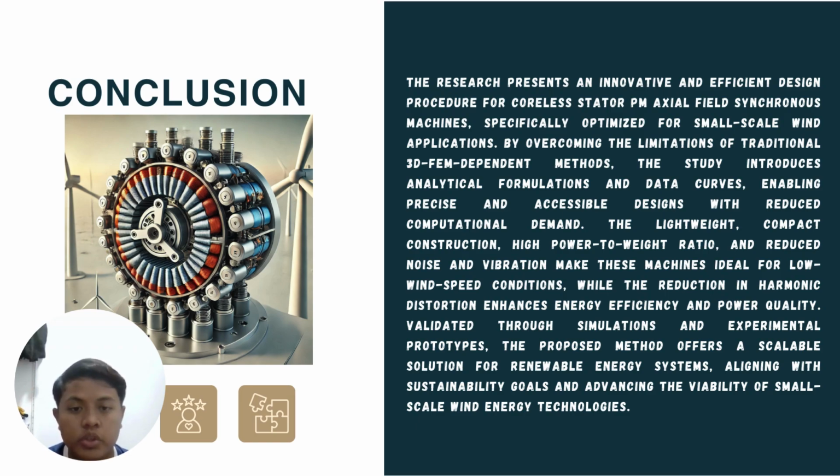Lastly, for the conclusion, this research presents an innovative and efficient design procedure for coreless stator PM axial field synchronous machines specifically optimized for small-scale wind applications. By overcoming the limitations of traditional 3D FEM-dependent methods, the study introduced analytical formulation and data curves, enabling precise and accessible design with reduced computational demand.